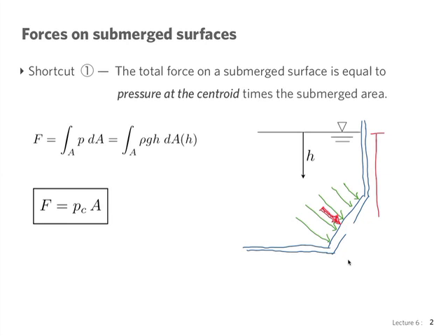There's an issue I need to be clear about: the resultant force we can calculate using the pressure at the centroid, but the point of action of that force is not at the centroid. The geometrical centroid would be somewhere, say, this point here. This is H of the centroid. But the point of action of the force is not at that point. That's what I'm trying to say.